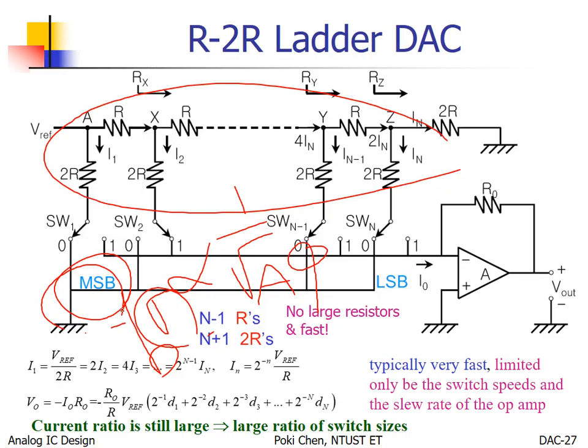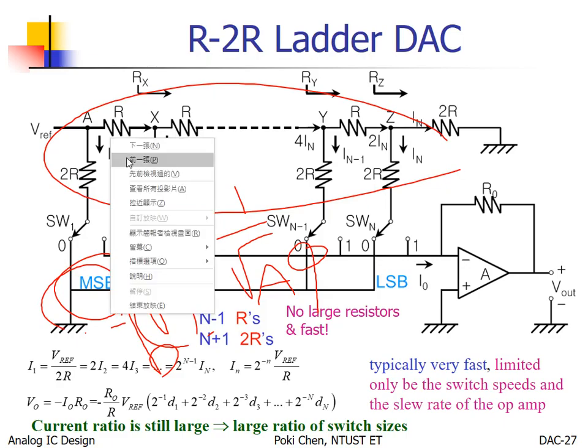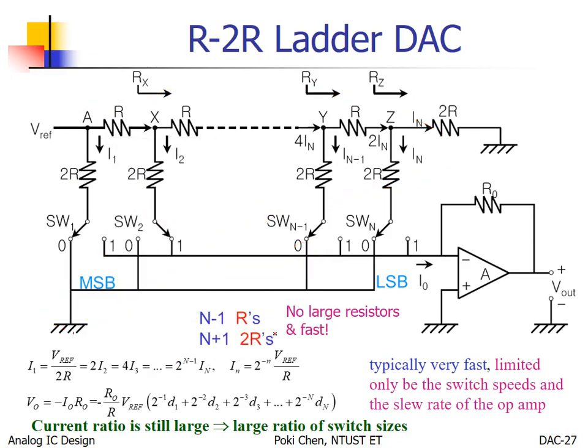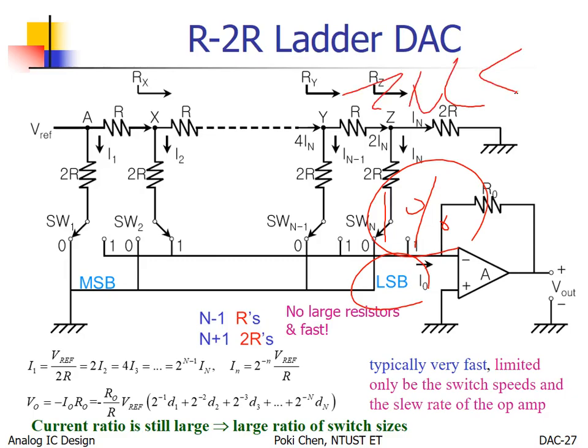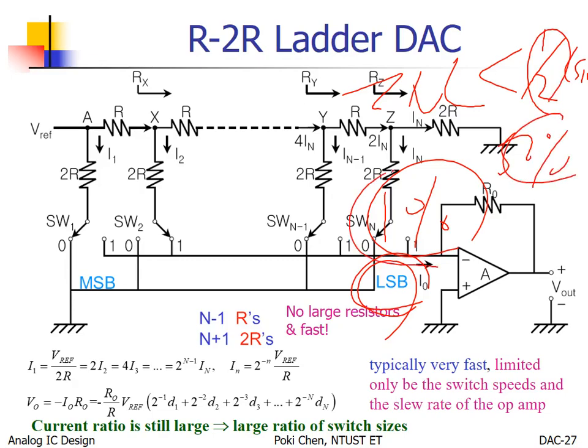Okay? For example, with the same area, you get 1% error, 1% of variation for your LSB. Oh, good enough. Why? Because for INL, everybody knows it should be, hopefully in theory, in practice, less than half LSB. Half LSB means 50%. Oh, very good. I have only 1% error in your LSB. Good enough, right? More than good enough. But the problem is not here.